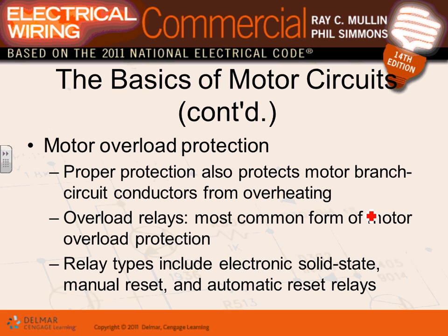Motor overload. When it comes to motors, you guys have done it with me. The first thing you need to do when it comes to any machine is have an overcurrent protection device for it. Then you have to have some type of a disconnect. Then you have to have a controller, then an overload, then you have your machine.